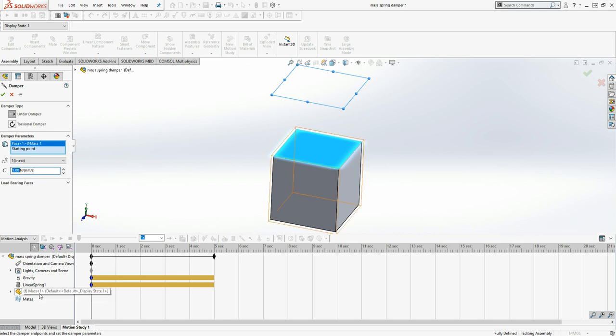So let's stick in a C value. Now, as we know so far from some of the stuff that we've done, the damping will always be at a factor outside of the spring stiffness. Now we're going to put it outside by a factor of about 100. So with that in mind, if you remember, for the K value we went 0.01. So what we'll do with this is we'll go 0.0001. So it's a factor of 100 out from the K value.